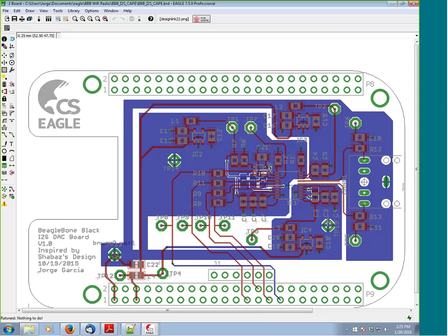If this was all tied together, there's a possibility it could move around to the other circuits and affect their noise immunity. So by doing this, all the currents do end up returning to ground, but they stay separate all the way up until here. And that's the goal of doing this separation: basically keeping noisy currents circulating in a certain area without having more quiet areas be affected by those noisy sections.